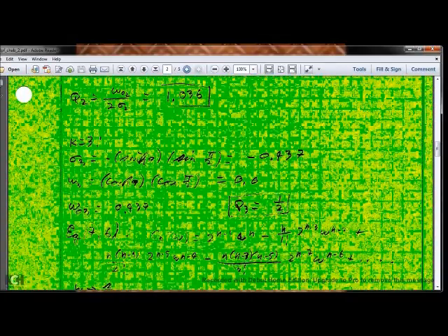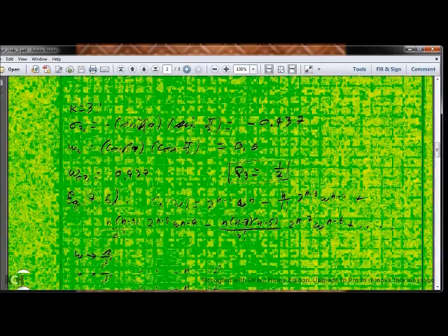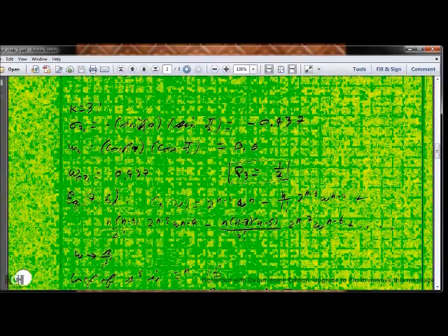For k equal 3, this is the first order section. The pole is a real number with no imaginary part. It's on the real axis. And we have omega 03, we found that. The quality factor for this odd pole is always going to be equal to 1/2.